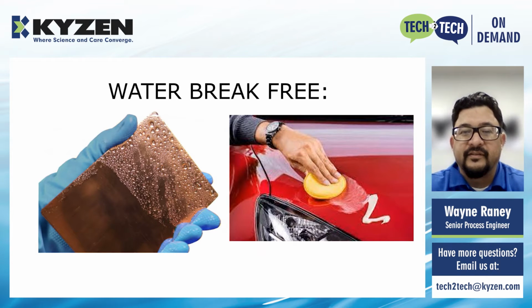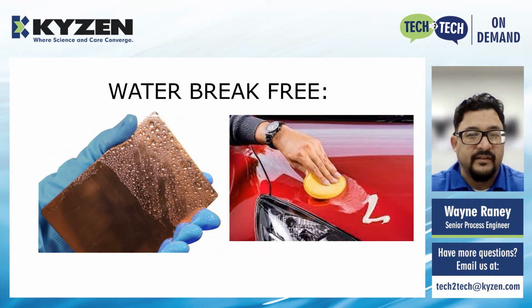When talking about wetting, think of washing and waxing your car. When you just wash your car with soap and water, the water sheets instead of beads. Thus, it'll be clean. If you look at the copper coupon, on the left part of the copper piece it shows to be sheeting off, and on the right is beading up. The beading is like after you wax your car. So you leave residues, these residues are left on the part. In the case of the paint on the car, this is a good thing, but when you're talking about industrial parts cleaning, it's not a good thing.